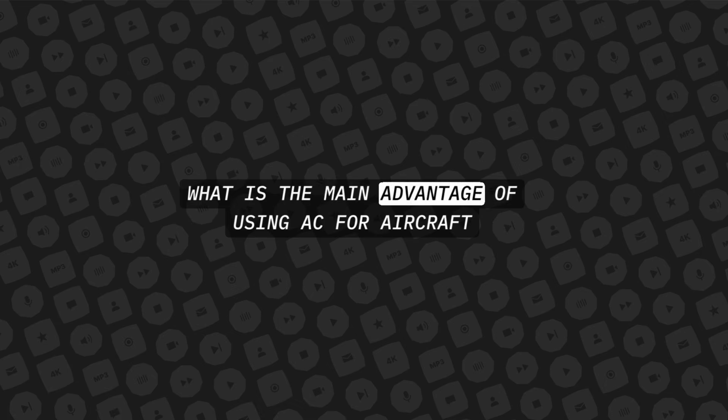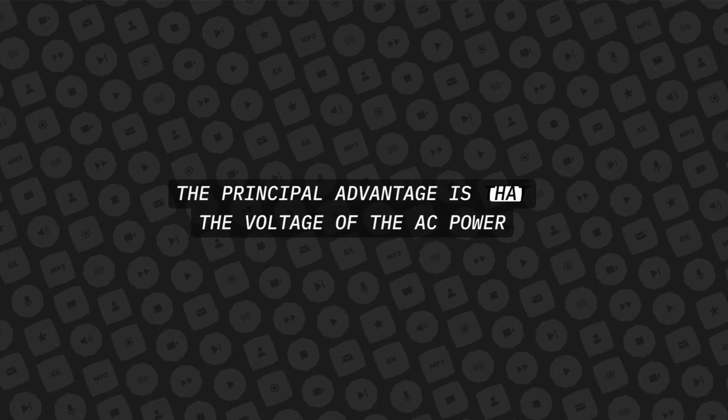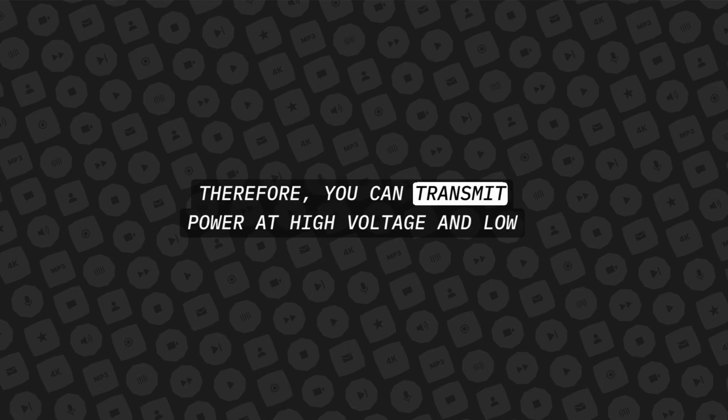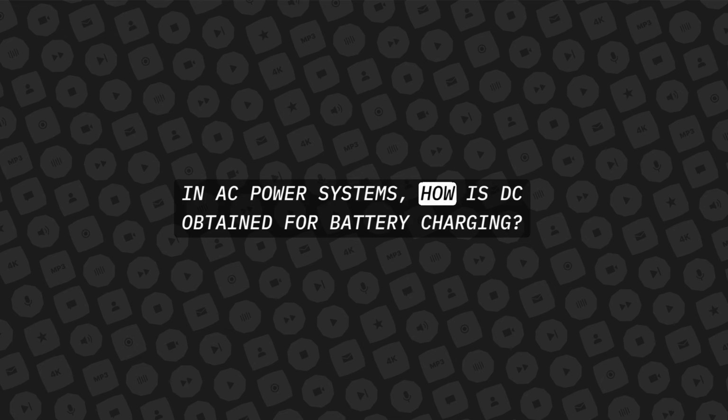What is the main advantage of using AC for aircraft electrical power systems? The principal advantage is that the voltage of the AC power system is easily changed using transformers. Therefore, you can transmit power at high voltage and low current, thus reducing the size and weight of the wiring in the circuit. In AC power systems, how is DC obtained for battery charging?